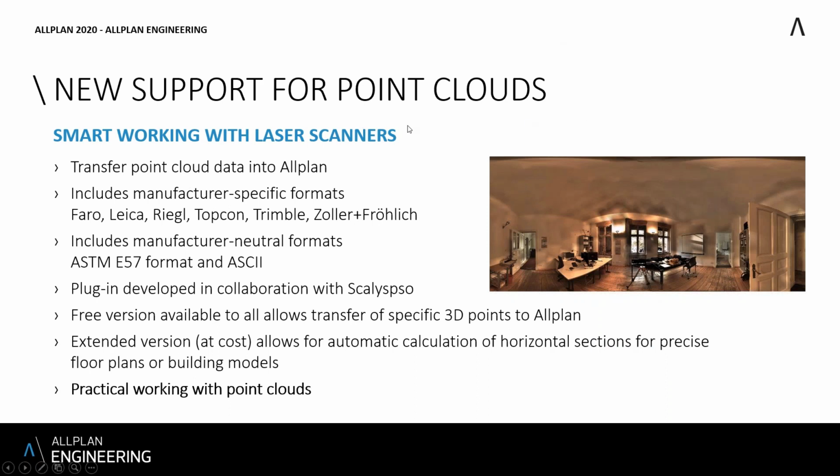And another aspect in this direction is the point clouds. So point cloud is very related to BIM. If you want to apply BIM to an older building, either you go on site and make some measurements, but that's not the best way to do it, and usually it's full of errors when you return to the office and try to redo the 3D model based on the measurements.